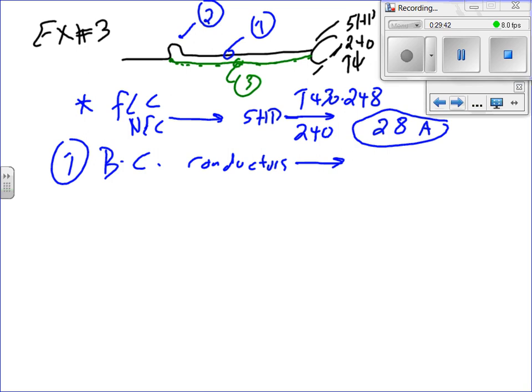The code says these motors are considered continuous. You have a pump, you can't tell the pump not to pump for less than 3 hours. If you need water, it's going to be pumping. If you need a fan, you can't tell them, okay, I'm going to cool you down, guys, for 2.5 hours, and then I'm going to turn it off. Normally you continue with whatever the load was.